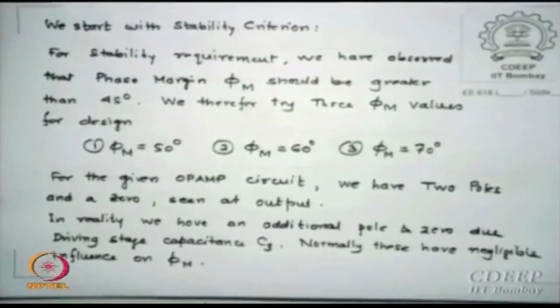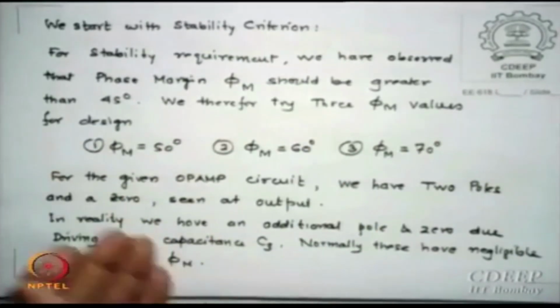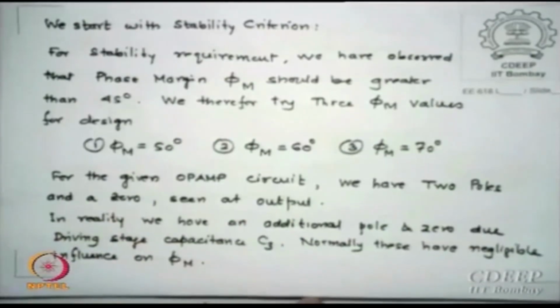99% or 99.99%, the CGS values are so small that typically, for example, 6 megahertz you are asking for gain bandwidth. I evaluated, I do not know whether I reached there today, it will be around 900 megahertz as your pole frequency. So 900 megahertz for a 6 megahertz gain bandwidth is far away. By the time 900 megahertz frequency comes, the gain would have gone to some minus 1000 dB kind of thing. So we are least worried about such poles and zeros.